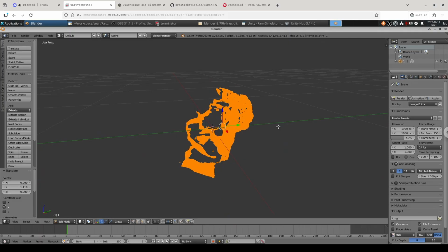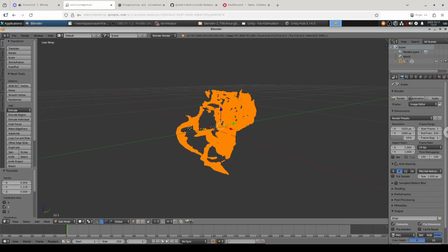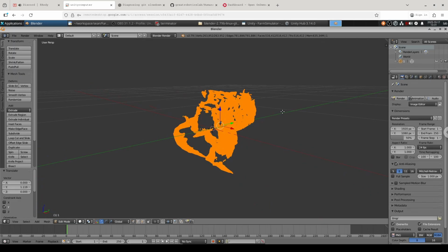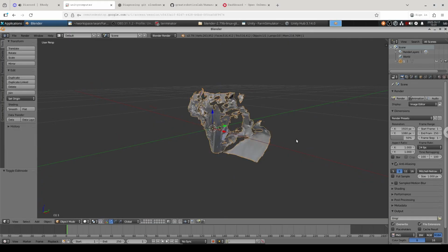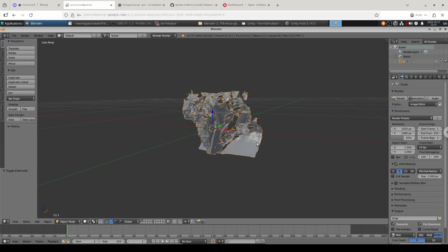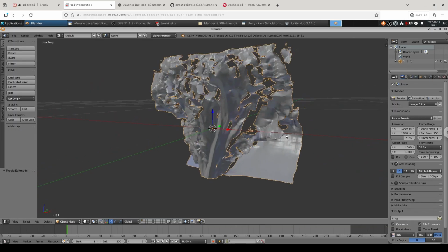And now, I think Blender works kind of weird, especially compared to Unity. So the green arrow is actually pointing backwards. So the opposite, I think, is the forwards direction. So you'll rotate it around the z-axis 180 degrees. So you'll do R, Z and then 180. And press Tab to get out of edit mode. And that should be in the right spot.